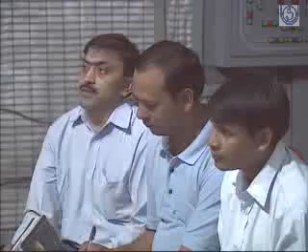And for industries? For industries, it will reduce his bill if the bill is on kVAh, or if there is a power factor penalty, or the demand is being assessed in kVA. Then his demand in kVA will come down. But for an ordinary consumer, his bill will not come down. That is why the consumers do not install capacitors, because his billing is not taking into account the reactive power at all. We don't have kVAh meters, we are installing kWh meters.